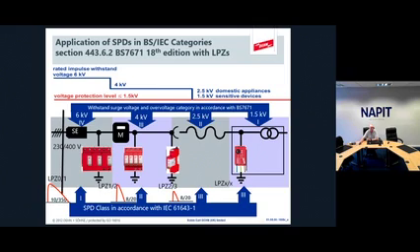And that's where I have another SPD, which is going to be in my further internal zone at sub-distribution. And that's where I'd fit, say, a type 2 device. And then closer to the sensitive equipment, I'll have either more type 2 or type 3 SPDs, and that'll ensure that any sensitive equipment just gets really low level surges, so everything's protected.